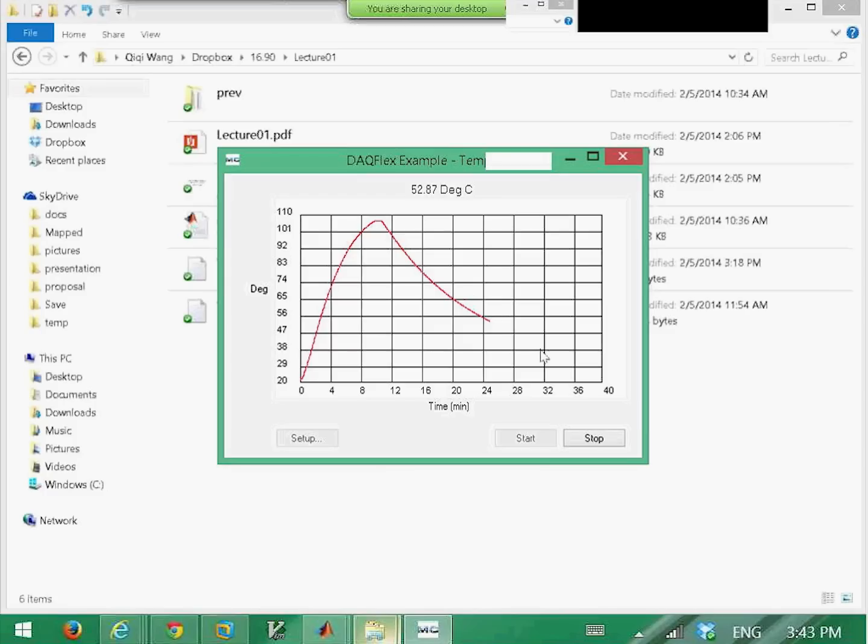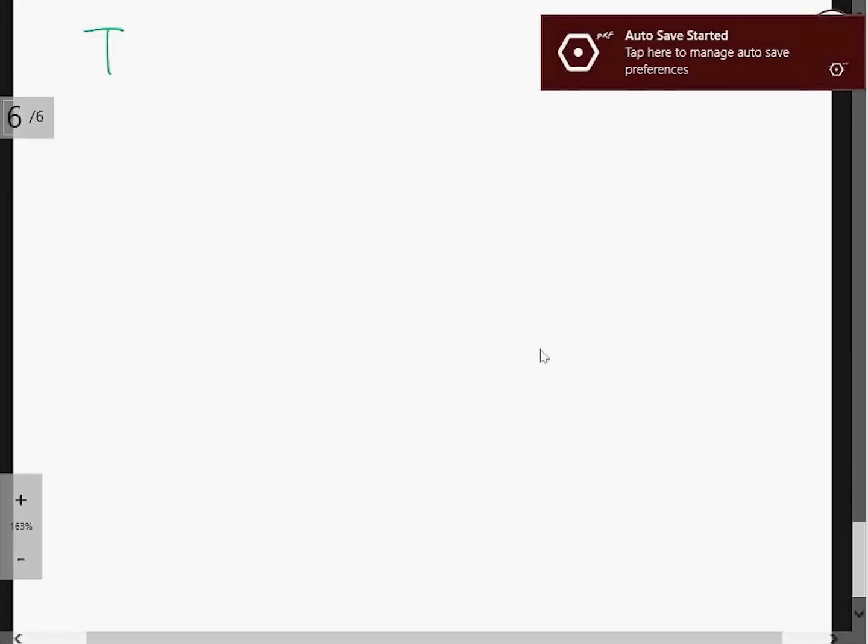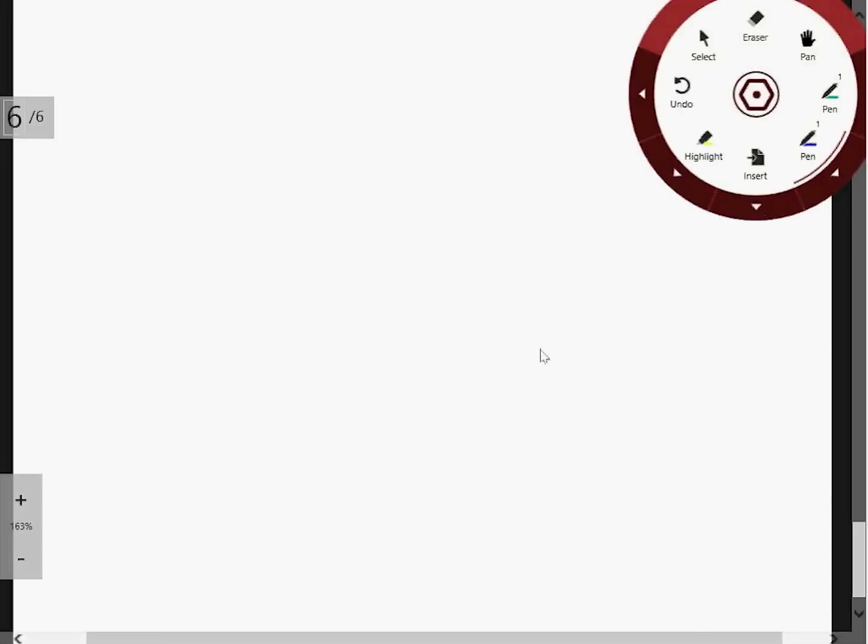So one can assume that the temperature distribution inside the aluminum is basically uniform throughout. When you look at the time history, it heats up so slowly, over the course of many minutes. The conduction inside the aluminum is actually much faster than that. So we can say that the temperature of the aluminum is only a function of time.